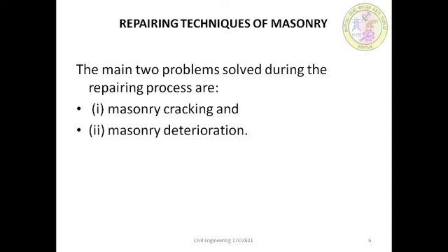Besides that, seismic vibration causes cracking through a moment or strain induced by imposition of loads, or by the restraining of volume changes in the masonry materials. Nothing can prevent such cracks, but at least they may be accommodated.